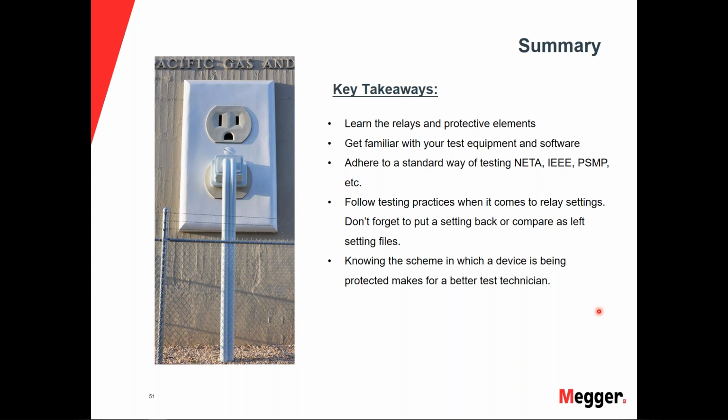Know the scheme in which your protection is, what you're testing. If you don't really understand what you're testing, then maybe it's very difficult for you to know the right and wrong from the relay test reports. If you're just going out there, running a few tests and handing in the document, and somebody else is overlooking you because you didn't really understand what you're testing, then you have to go back out there.